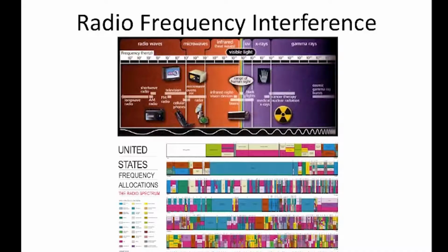As far as intentional limitations to the frequency response, there are some practical limitations that as designers you have to be wary of. For example, radio frequency interference. We do not want to get RF into our design. If radio frequencies get into our design, even if they're very high frequency, they can be intermodulated down into the audio band and cause noise and other sorts of interference and problems with the circuit. So it's a good idea at the input and output of a microphone preamplifier to do something to avoid getting that high frequency information into the circuit.